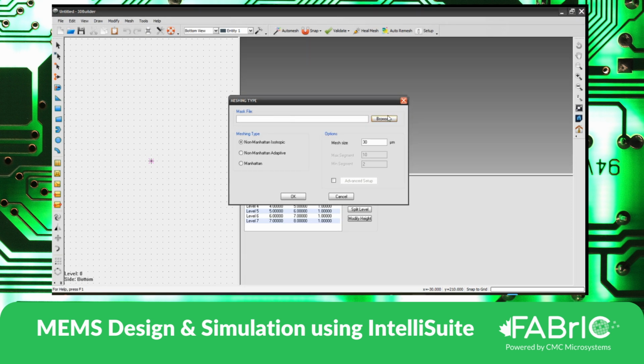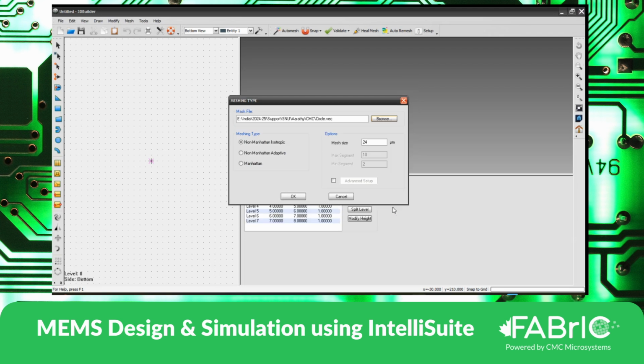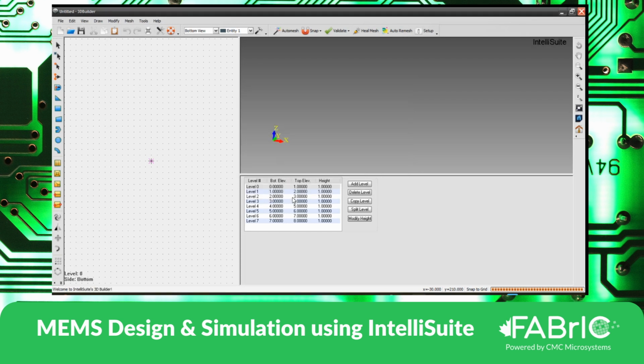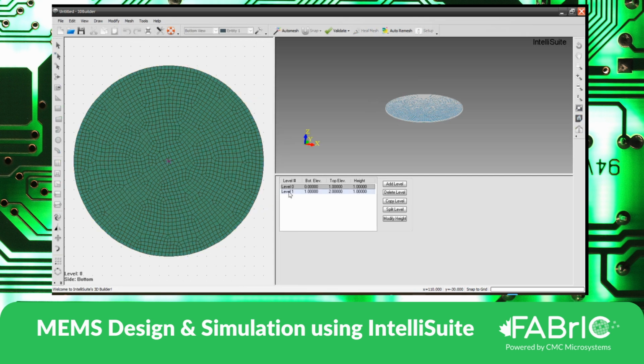Automesh, browse, circle. So now the question is which mesh to take. It's a circular geometry, so obviously we cannot take Manhattan. So whether it's isotropic or adaptive, isotropic is what by default I would recommend. Then click OK. So this creates a tetrahedral structure, which is layer one above the other.